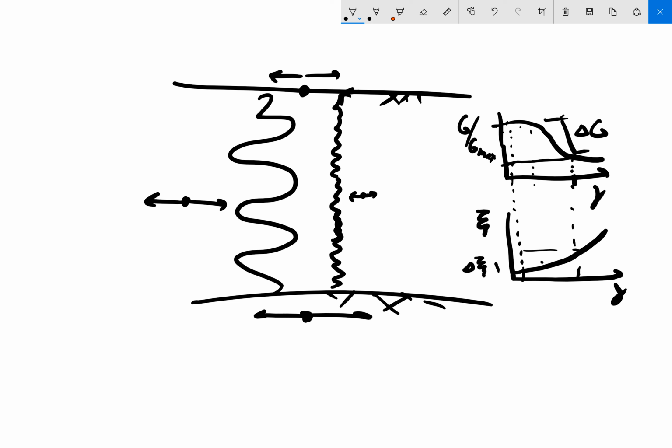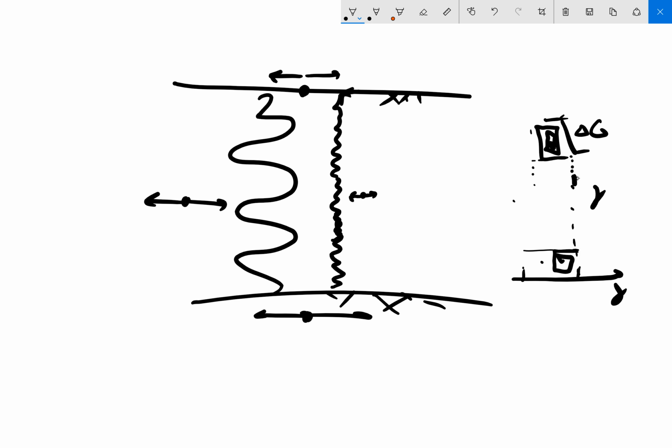And remember with equivalent linear, I'm trying to do this iterating approach, where I try to zero in on a solution. If that strain is too big, then the equivalent linear approach is going to give me some really wonky values and stuff that aren't really going to be realistic and I can't trust.